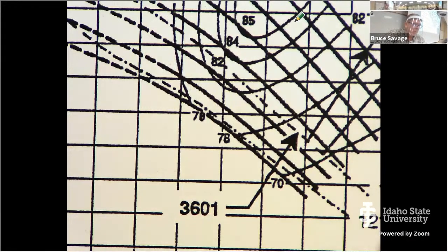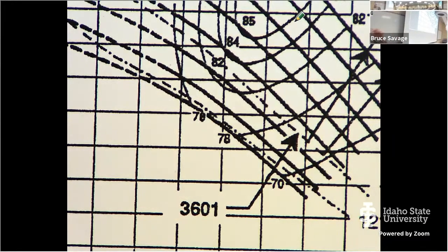So basically the 154 will handle all the way until you get out here where you're going to need the 295, supposedly. I don't trust those too much. I prefer to do the calculation myself to figure out what I need, but that's supposed to be a quick reference of what motor I need with my pump. Now I would note that not all pump curves look like this. Before I leave that, any other questions on pump curve basics?